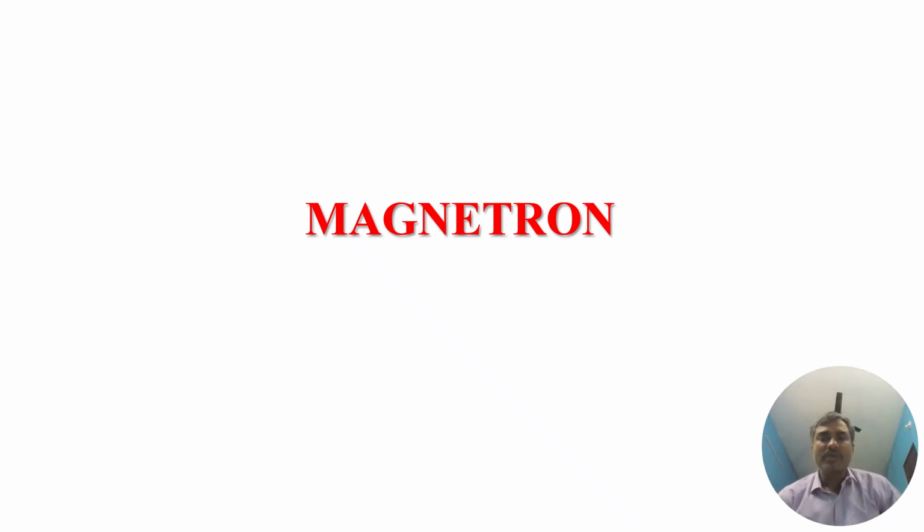Dear students, today we are going to discuss the construction and working principle of the magnetron oscillator. The magnetron oscillator produces microwave signals in the frequency range of 1 GHz to 100 GHz, and it uses an M-type tube. It is also called a cross-field device because in the cavity gap the magnetic field and electric field components are perpendicular to each other, and it is mainly used in radars, industrial heating, and